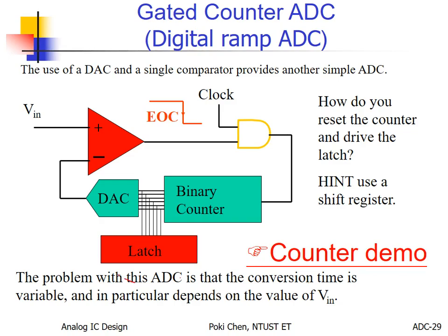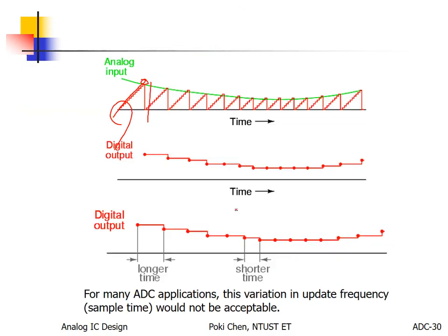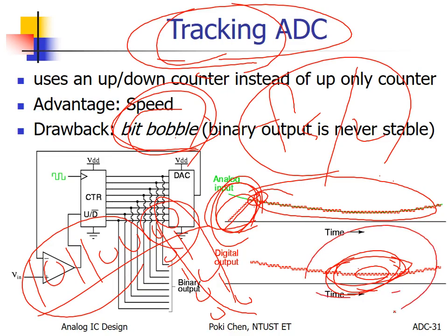The latch. When you say okay to latch the output, to latch the counter to be your output. Never mind, you focus on falling edge or rising edge, but not both, please. Only one. You can choose rising edge or falling edge to latch the output. Bingo. This problem will be solved very, very easily.